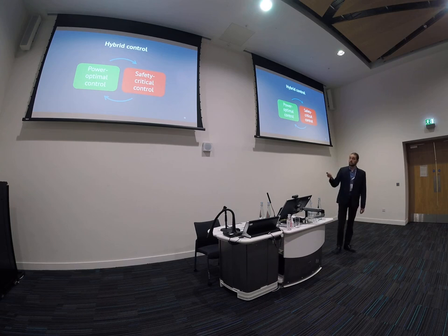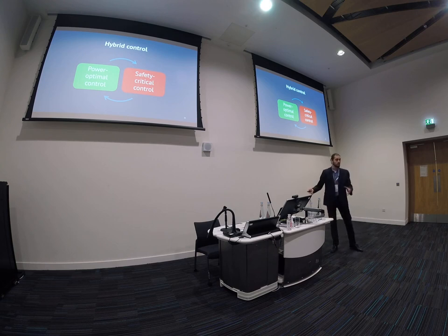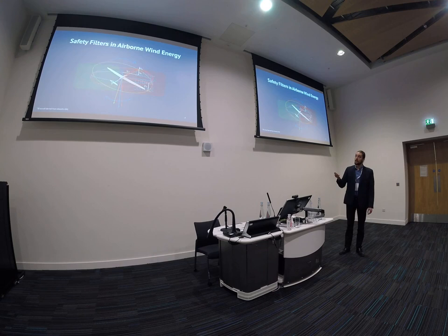analysis. And then we use this hybrid control setup, so we design it as a switch system, and whenever the safety filter detects that potentially we're going to, in this case, have tether rupture, then we switch over to the safety critical controller. Of course, when we have these switch systems, we have all of the complexity and the challenges that switch systems provide. So in this case, we have to use a mixture of sliding modes and hysteresis switching in order to get that safe switching there.